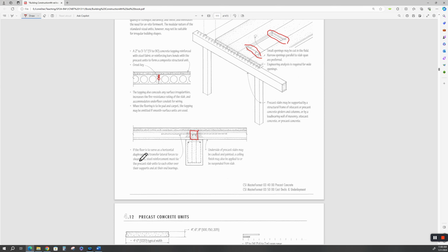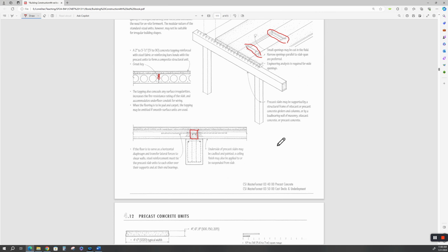But here it's a span, okay? And in between here, we'll put reinforcing bars. And when we pour this floor, it'll pour down through here. Now, if this is an end cap run, we'd have to put forms out here, right? And they have pre-made forms that do that.